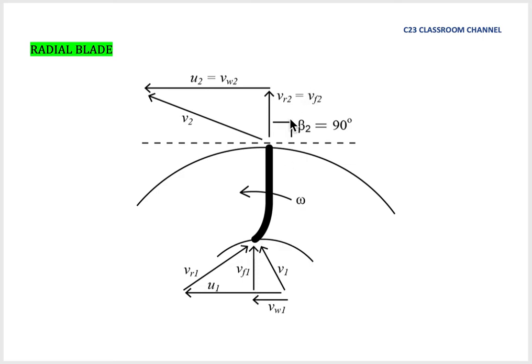And then at the outlet here, we must first draw the absolute velocity V2. So we draw something like this, an arrow in this direction, and we label it as absolute velocity V2. And then we know that the relative velocity, the velocity that flows relative to the shape of the outlet blade here, will be straight like this because the blade is 90 degrees.